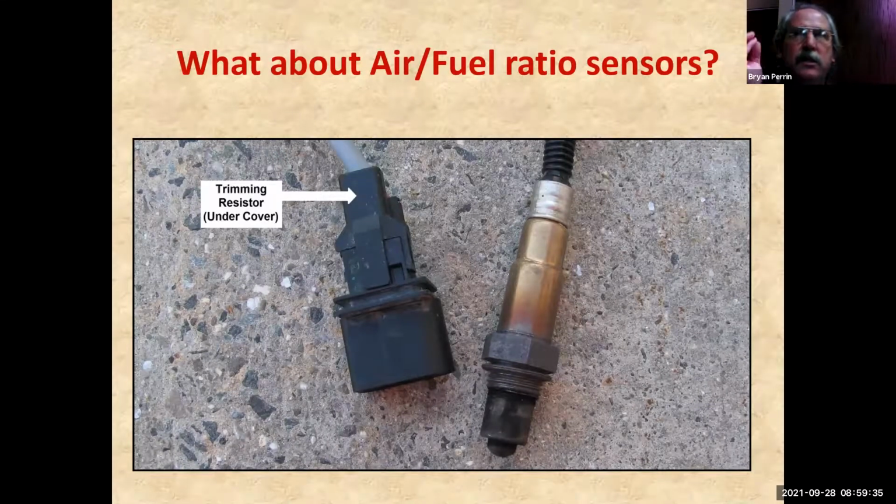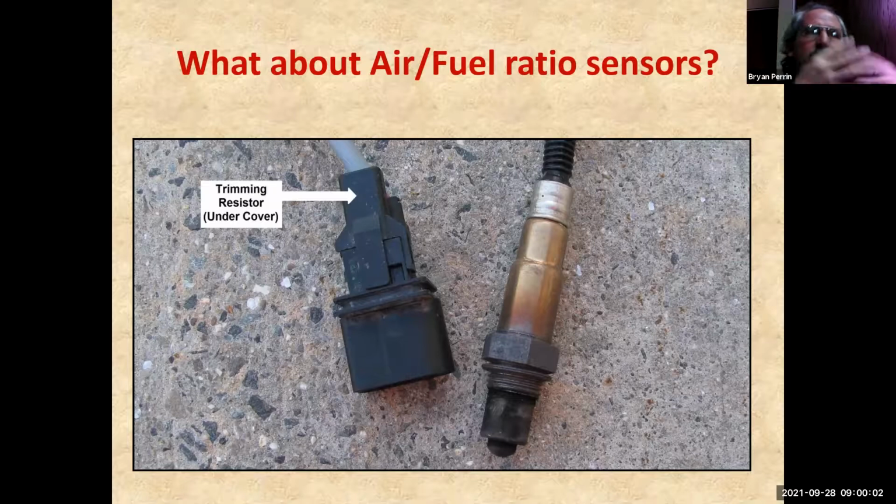If it has the Denso style sensor, where it's a normal four-wire connector, it may or may not have rear fuel trim. Certainly if it's 2010 and newer, I would expect it to. I'd be very surprised if it didn't. Between 95 and 2010, you know, who makes it? If it's Toyota, I can guarantee it does. Volvo and Rover, I've seen them do it pretty early. I've seen a lot of others, but again, it has to at least be on the table.